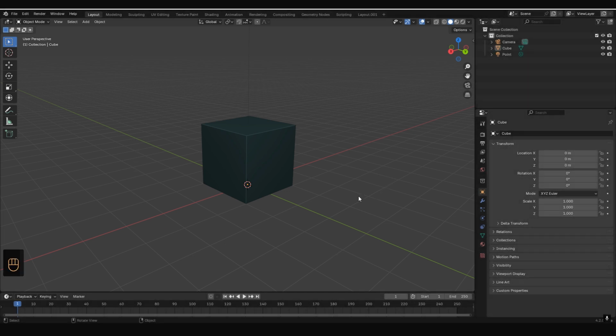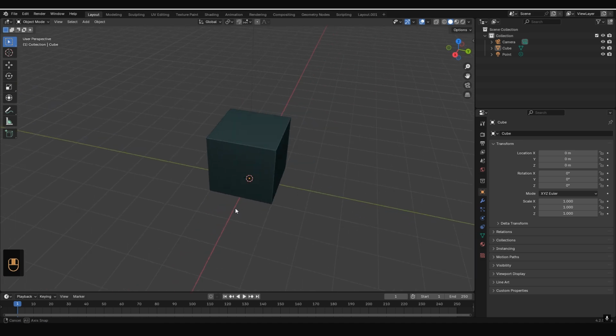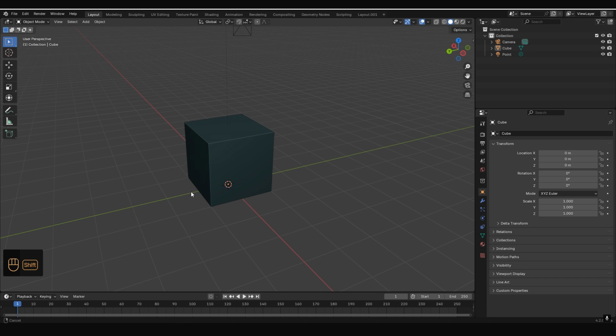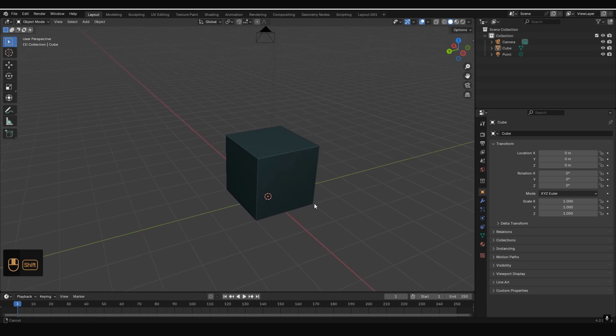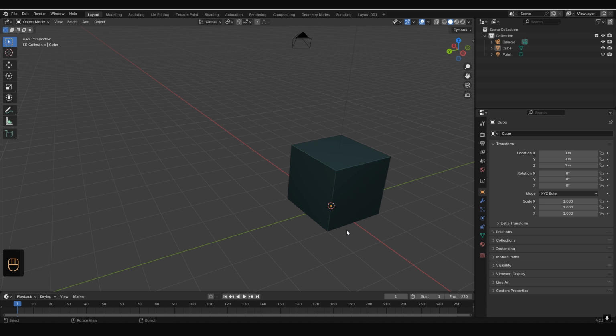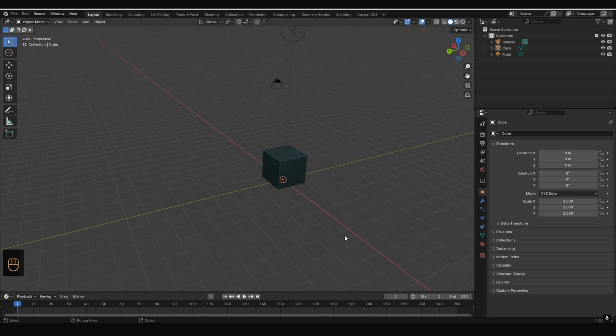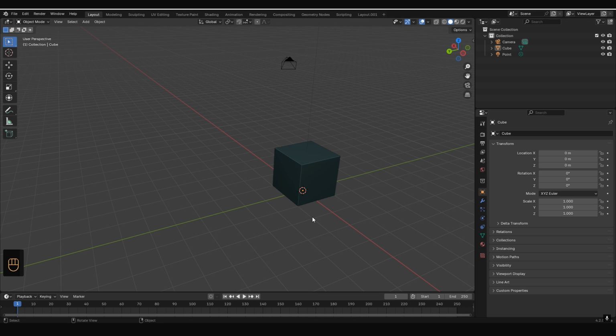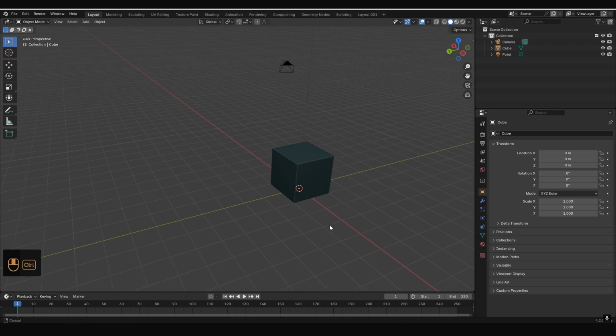To fly the camera around an object, click on the mouse wheel and move it in the desired direction. If you hold down Shift in the mouse wheel, you can move around the scene. You can zoom by rotating the mouse wheel. Holding down Control while holding the mouse wheel makes the zoom smoother.